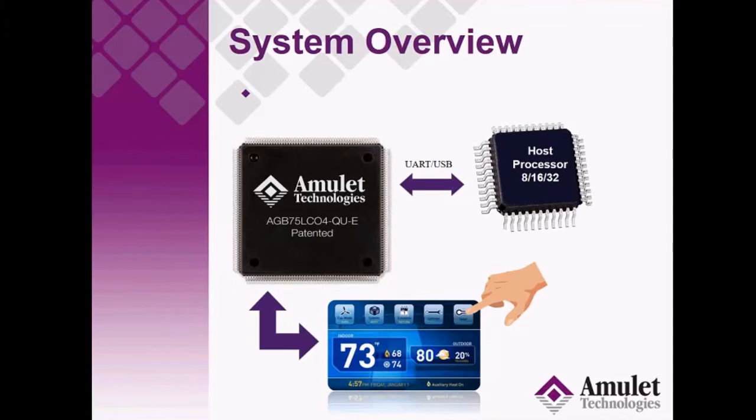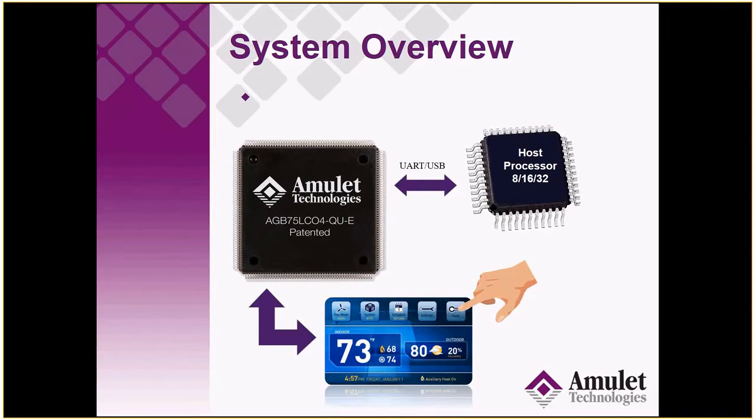The Amulet chip drives the LCD display, and also reads the touch panel information and abstracts all of that away from the user, from the host processor. The host processor talks to the Amulet system over usually a UART or USB channel. There are some other ones as well. On some of our boards we have RS-485 or RS-232 or I2C or SPI that are also available.